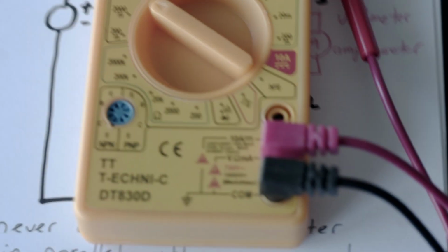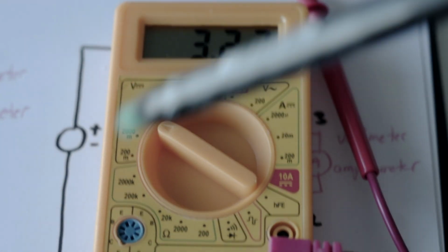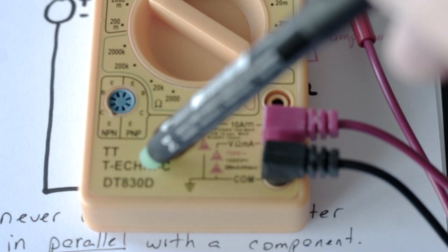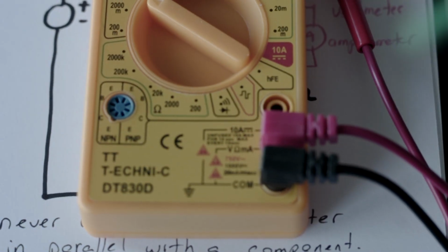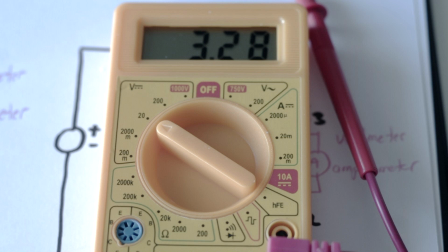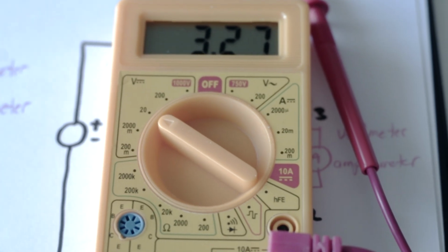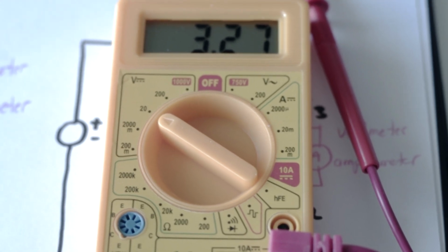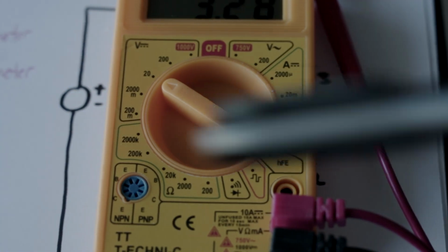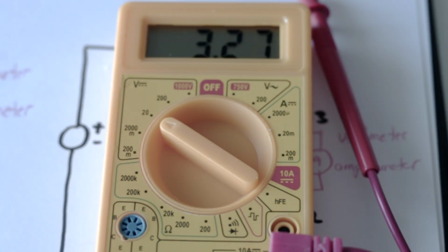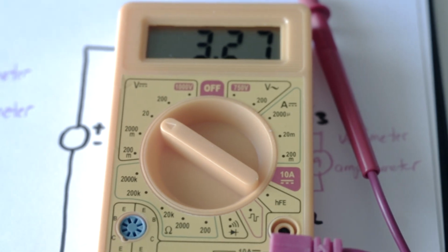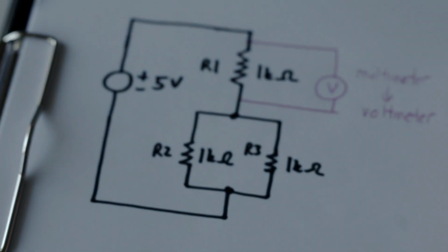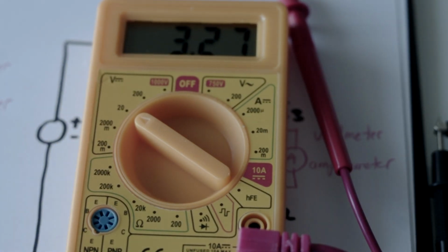Okay, but of course, in reality, the multimeters don't have infinite internal resistances. You can find out their resistances by looking up their instruction manuals online or through the instruction manuals in the lab. Usually you see on the order of 10 mega ohms or so. So it means one thing. If you are measuring large resistances, then you need to be careful about the internal resistance of the multimeter. Actually, you can try, for instance, doing a similar experiment to the one we do here by using a 1 mega ohm resistance and see if there is anything different. Okay, that's an interesting experiment.